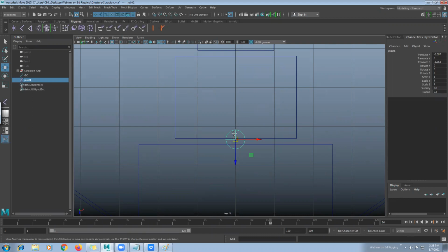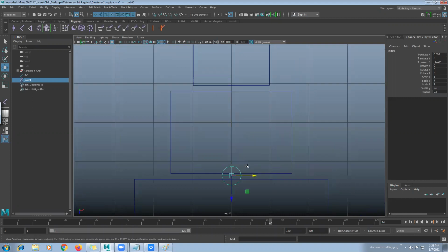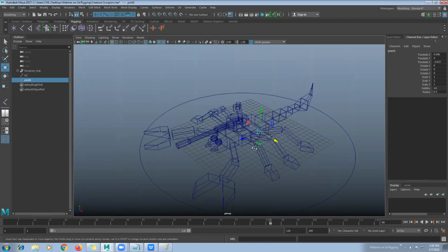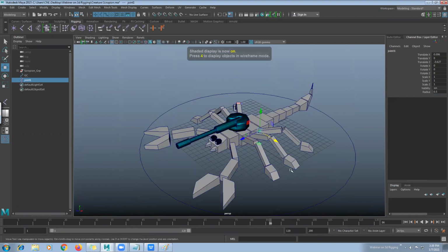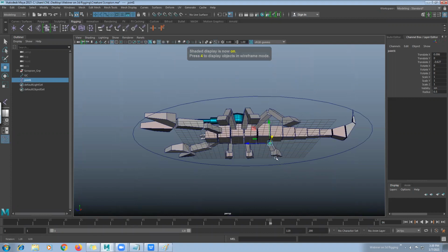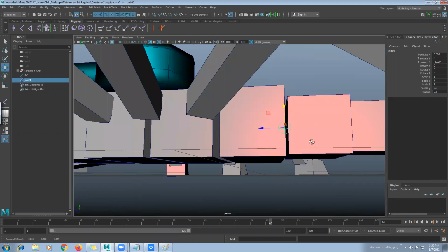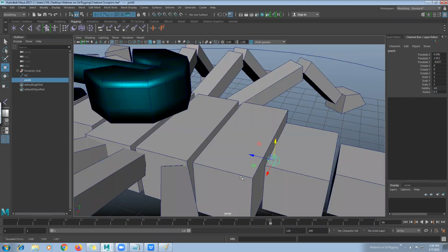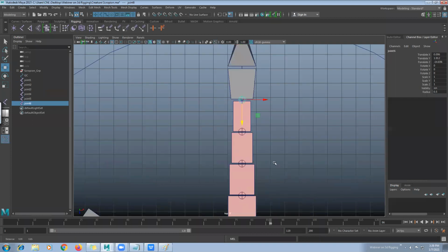Okay, I just place them as per my requirement. That doesn't mean that you have to put all the bones in exactly the segmented way. You may put your bones wherever you want. Okay, so I just copy it. Before copy, go to the perspective and check what the location is. Now it's very much on the downside, so we should not do that. Put it here, go to the top view, and we drag it, Shift D, and just duplicate many times.